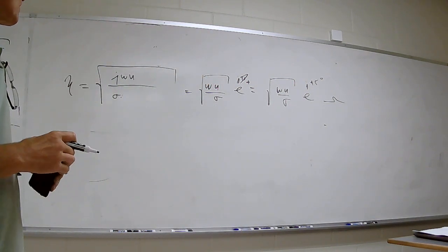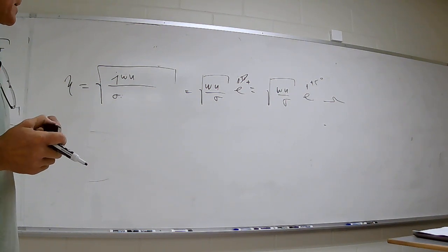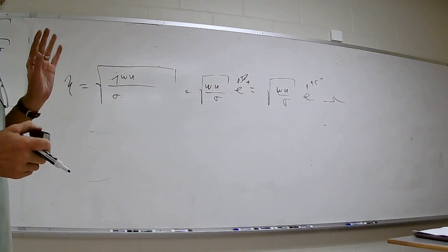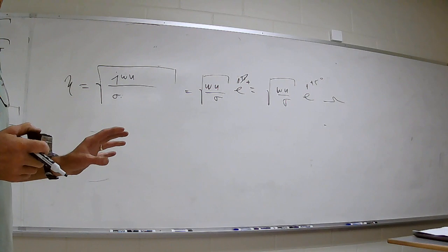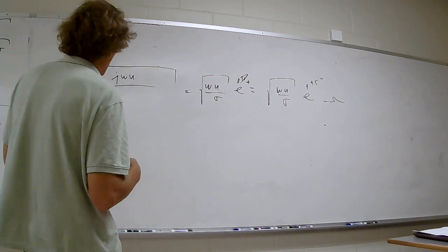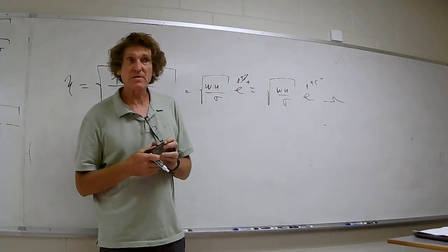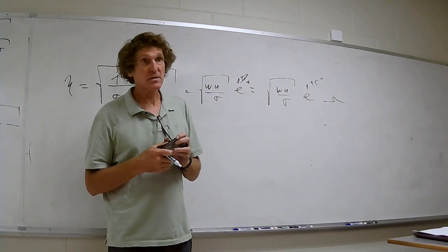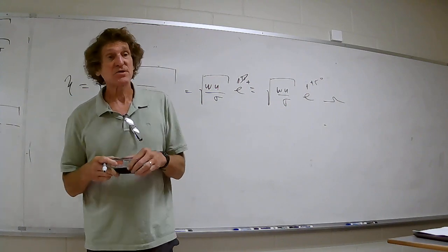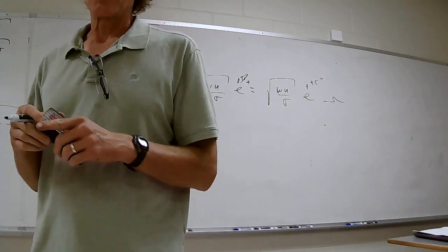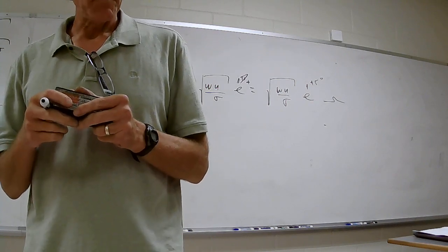Now, anytime you have an intrinsic impedance that has an imaginary value, you know it's lossy. So, look at this. This is for a very good conductor. And in a very good conductor, the phase angle is 45 degrees. It's a big loss. I'm just telling you, that's a lot of loss. We saw that alpha and beta for a good conductor would have the same magnitude. It'd be the square root of pi f mu sigma.